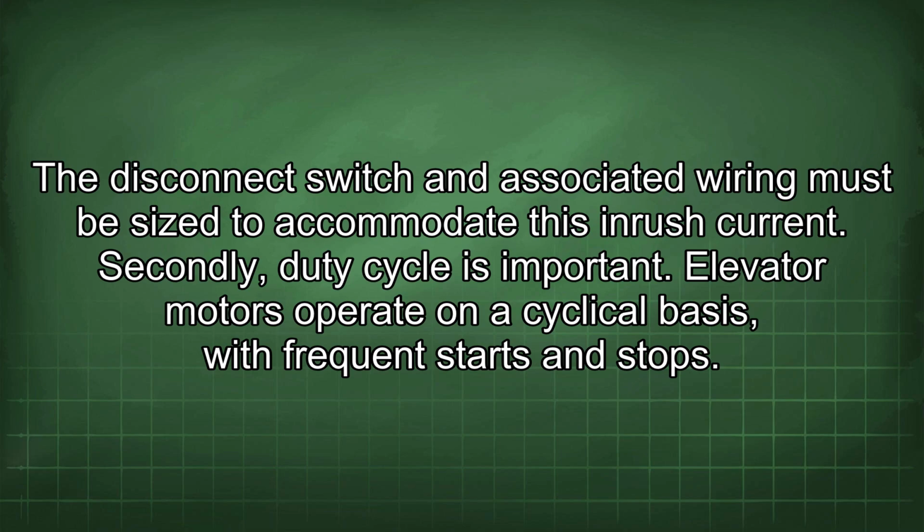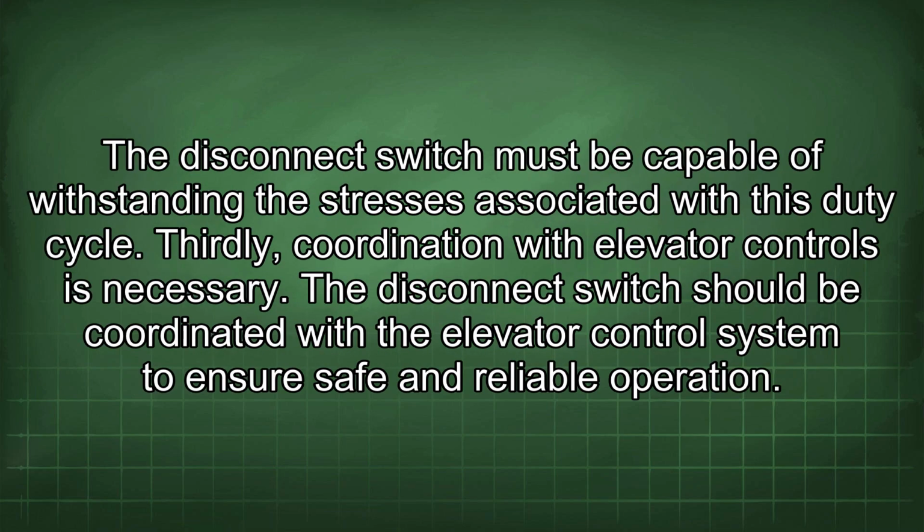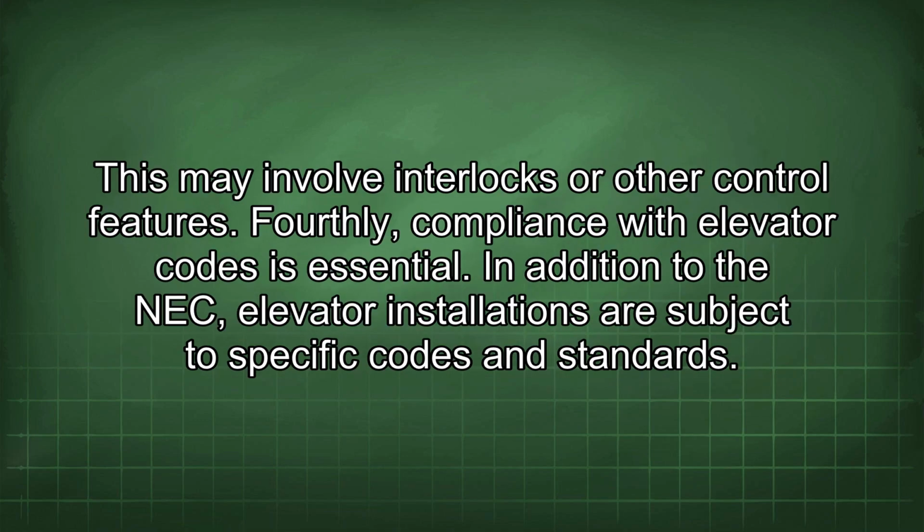Secondly, duty cycle is important. Elevator motors operate on a cyclical basis, with frequent starts and stops. The disconnect switch must be capable of withstanding the stresses associated with this duty cycle. Thirdly, coordination with elevator controls is necessary. The disconnect switch should be coordinated with the elevator control system to ensure safe and reliable operation. This may involve interlocks or other control features.